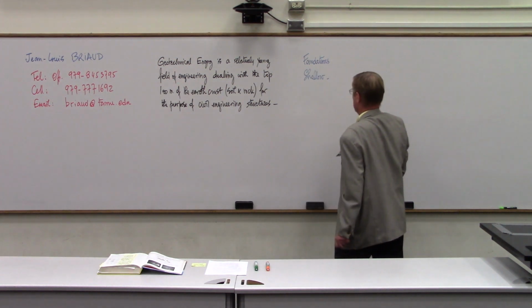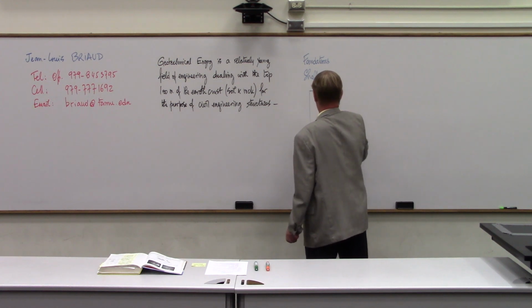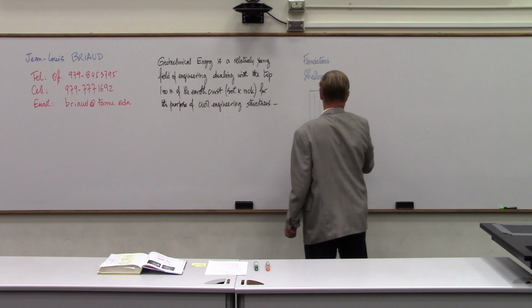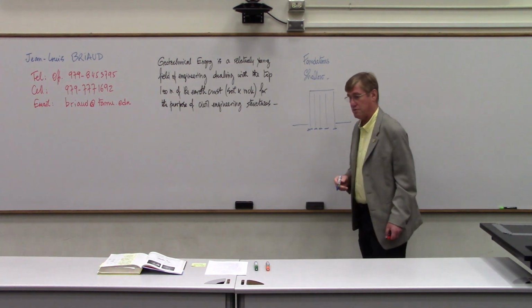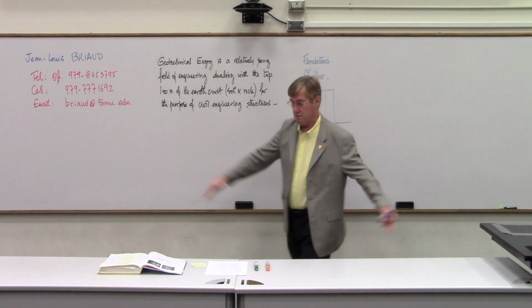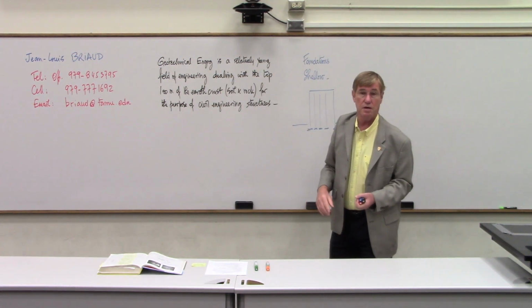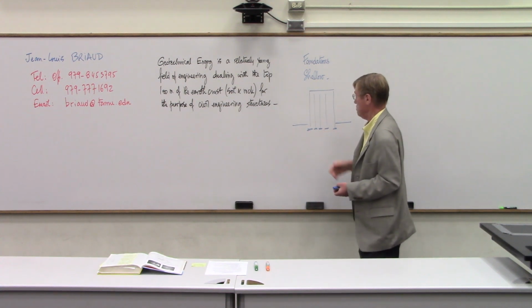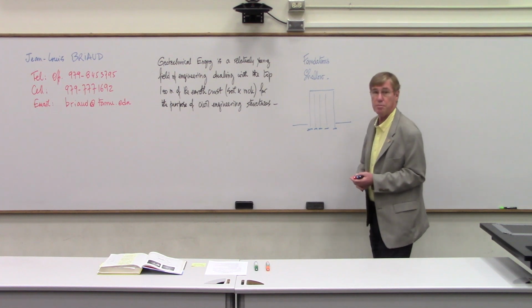So, for example, you might have a building, and this building has columns, and each one of those columns is on a spread footing. Also, a piece of concrete. This building is actually on spread footings. They're about 3 meters by 3 meters by about 1 meter thick. And the columns rest on these concrete footings that rest on top of the soil.